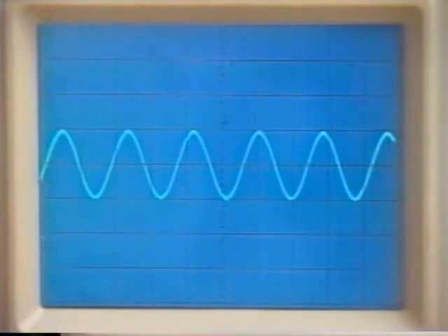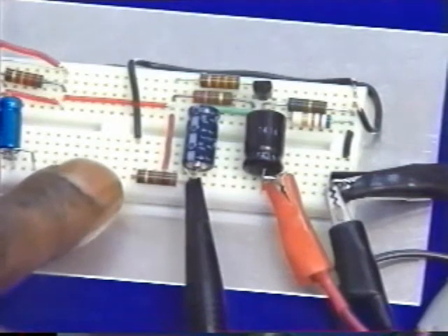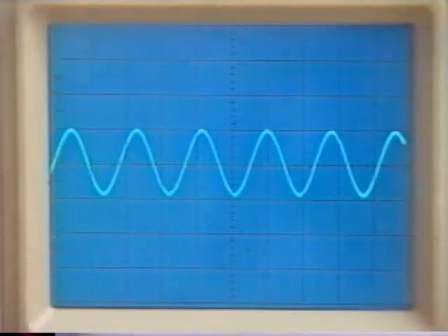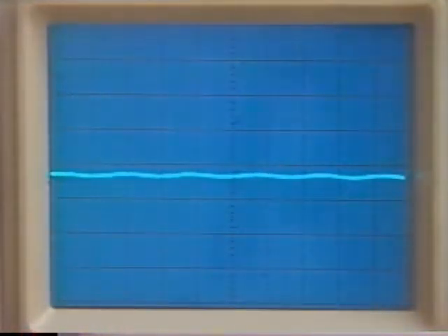The oscilloscope looks like a very high resistance load, which, remember, will not be a problem to a voltage amplifier. But now notice that when a 100 ohm load resistor is connected to the amplifier with the high output resistance, the output drops considerably. This means that the amplifier is not capable of driving a signal into a load as low as 100 ohms. In this case, the amplifier is severely loaded down.